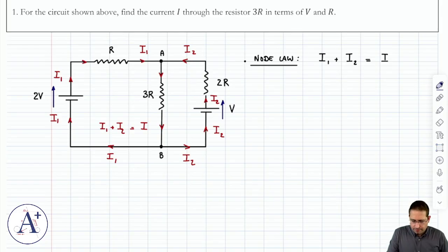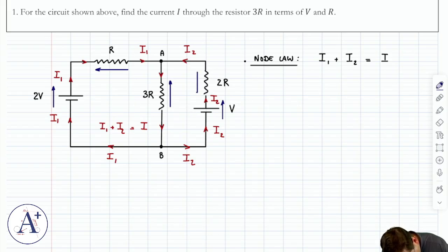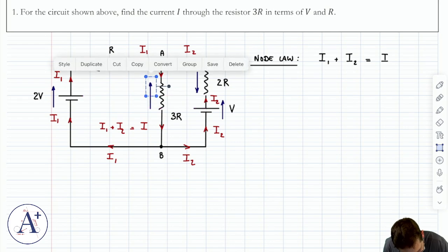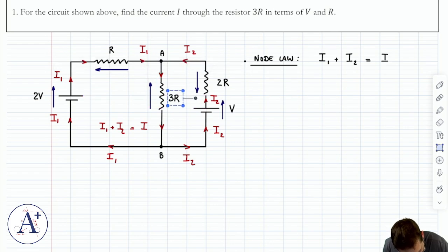And this is 2V. For resistors, the rule is that the voltage arrow will always point from minus to plus, but it's a little simpler for resistors to say that it points opposite the incoming current. Okay, so it points opposite the incoming current, like this, and like this. And just allow me, in anticipation, to do this. It makes no difference. It's just to have enough room to write everything out.